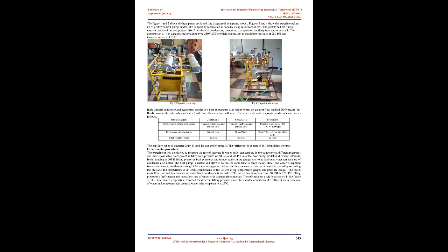In the present study, the modification of the heat exchanger and experimental performance evaluation of a vapor compression prototype heat pump model was carried out. By modifying the heat exchanger, improvement in COP is observed. The variation of speed of compressor and evaporator affects the performance of the heat pump. The experiment was conducted to evaluate the water outlet temperature for different mass flow rates, different refrigerant filling pressures and evaporator fan speed.